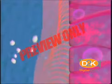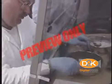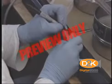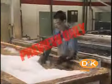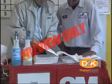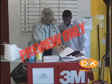Pool chemicals can also be corrosive. Corrosives are materials that can attack and chemically destroy body tissues on contact. Corrosives can also damage or destroy metal. The effects on tissues and metals depend on what the corrosive agent is and how concentrated it is. They can begin to cause damage as soon as they touch the skin, eyes, respiratory tract, digestive tract, or the metal. Material safety data sheets, also known as MSDS or product labels, should be consulted for the specific effects on tissues or metals and for procedures to follow in case of spills or splashes.